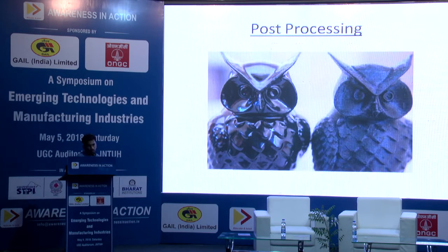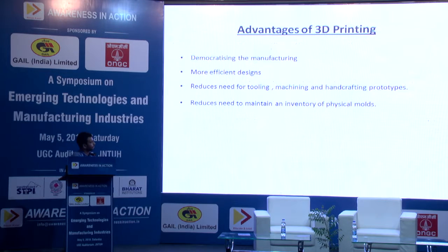There are a lot of post-processing machines currently available where you can get matte finish and glossy finish. This goes with this particular technology, like the FDM process. If we talk about SLA and SLS, we need the cleaning of the part, but not the post-processing, as in not to entirely change the aesthetics.